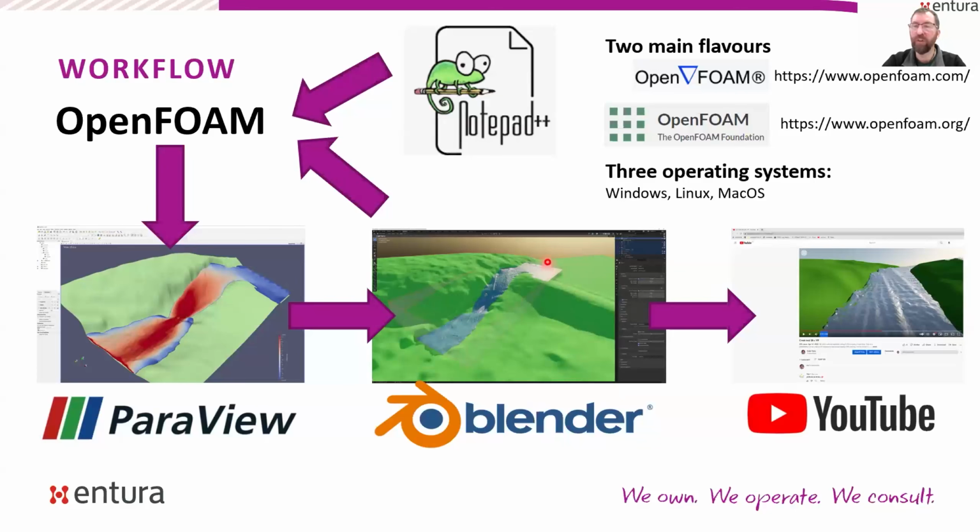And because you're dealing with pieces of code in terms of text, you're dealing with text editors, so you might use something like Notepad++. And using those two pieces of software, which also happen to be free like OpenFOAM, you can generate the inputs that you might need and then run one of the solvers in OpenFOAM. And as Ray mentioned, interFoam is one of the most common ones for civil engineering applications, which I often use, where you're dealing with air and water, and it's a multi-phase flow.